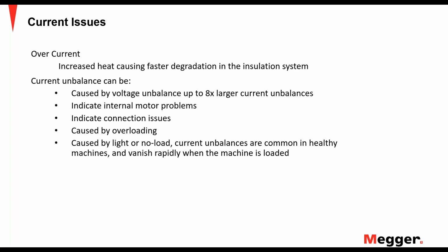It can be caused by overloading. It can be caused by a light load or no load. Current imbalances are common in healthy machines and vanish rapidly when the motor is loaded. So again, noting the loading of the motor while we have a current imbalance is important.